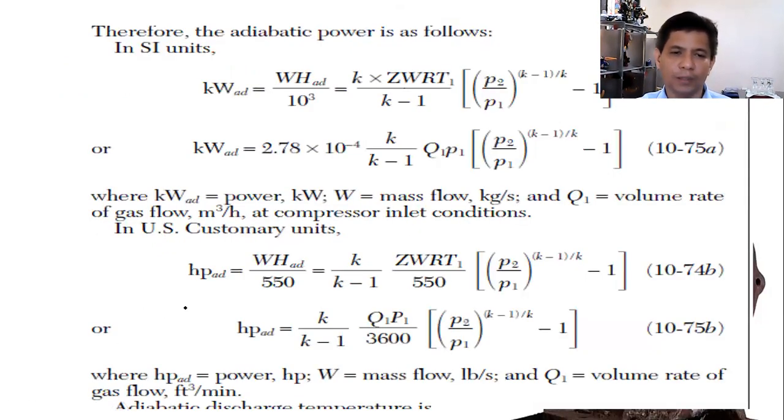And if you want to solve the horsepower, you just follow this equation from the handbook. This is from chapter 8, 10-74. But it's very hard to put this in memory, no? So generally, our experience is we use the Cp delta T equation, and then we use the power is equal to m dot times delta H, or Ws divided by the efficiency.